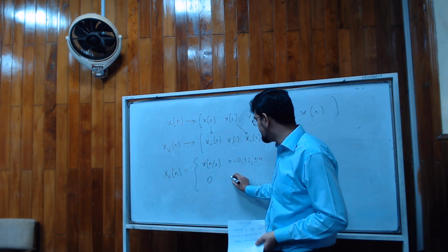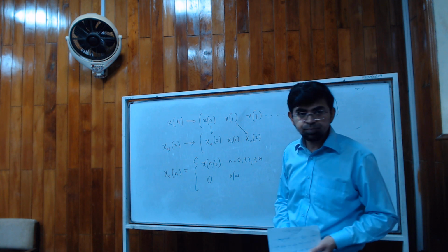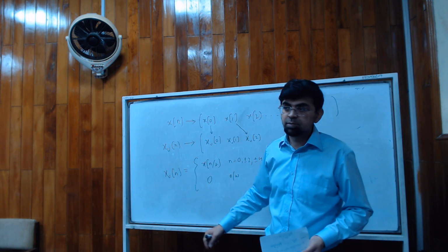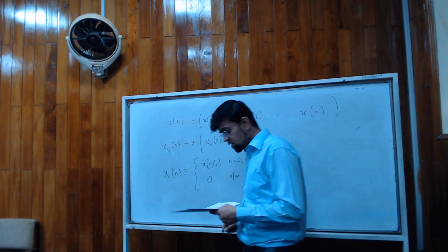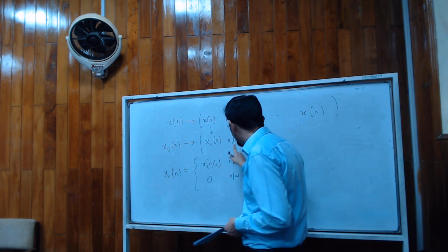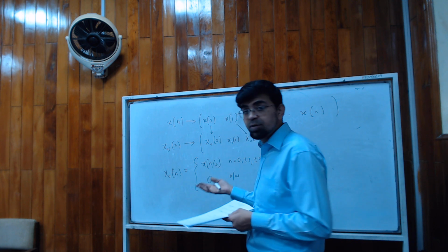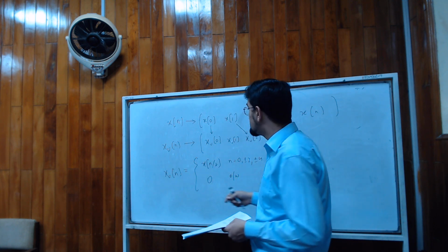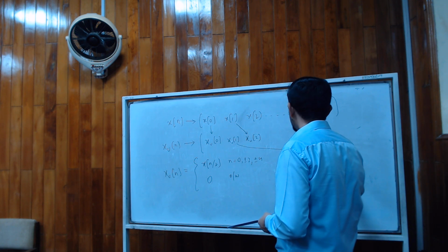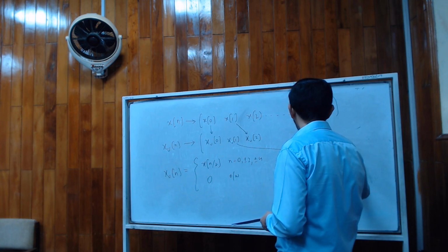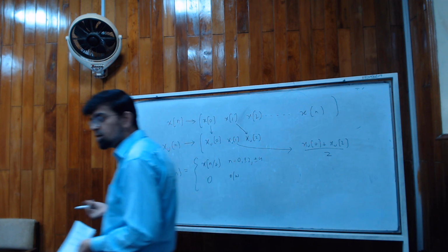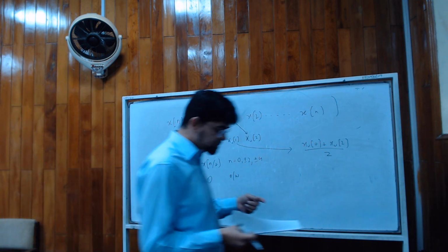So first you are adding zeros. Yes, ये पहला step है. First you add zeros. We call this zero padding. You are putting zeros in between. They are just placeholders. Now in the next step, you will replace these by some sort of interpolator. The simplest interpolator would be to average the one to its left plus the one to its right, divided by 2. This is linear interpolation. So this way you can do upsampling.